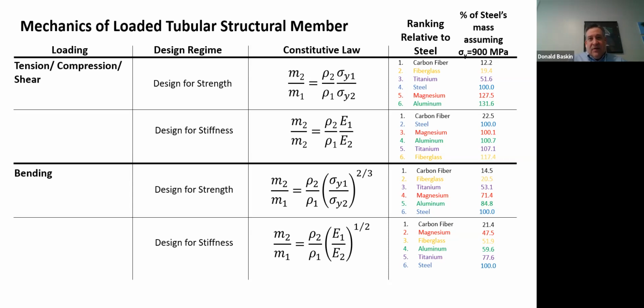For example, there's an Italian bicycle parts manufacturer named Campagnolo that makes crank arms out of a randomly oriented carbon fiber mix. They take loads in different directions and they don't fall apart. But ultimately, I'm not sure they're more structurally efficient than really high quality, well-engineered aluminum parts, and they probably cost a lot more.